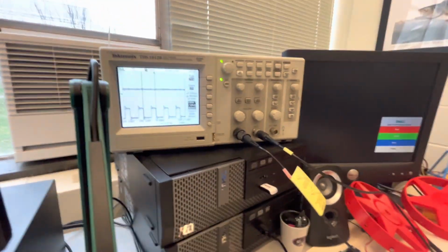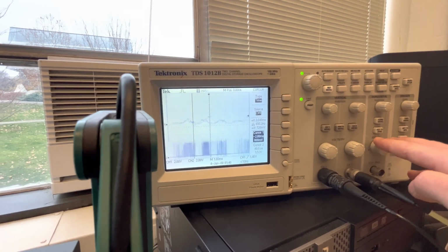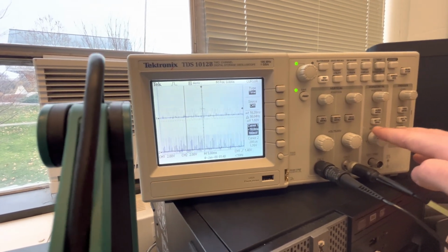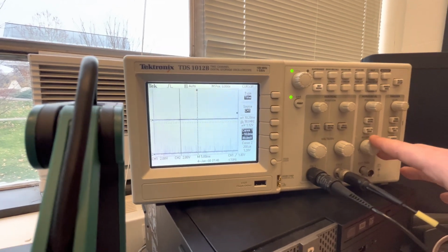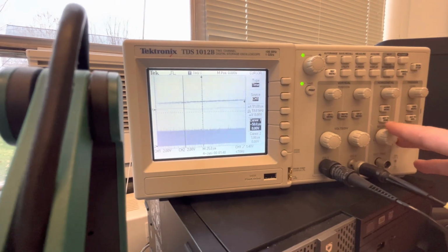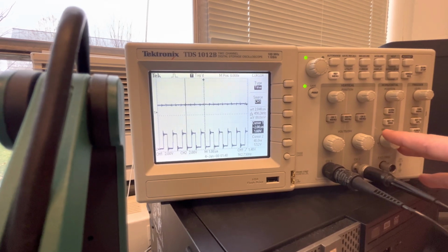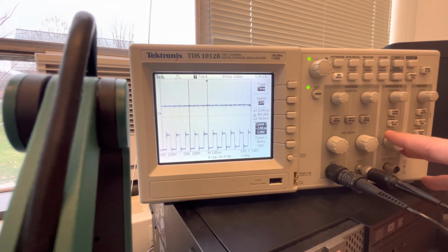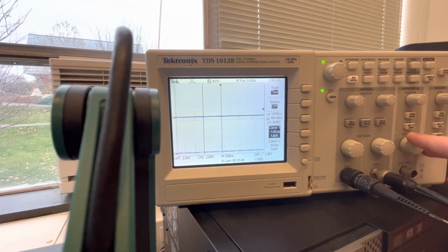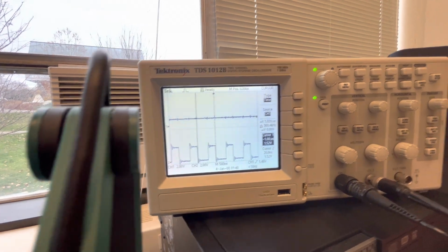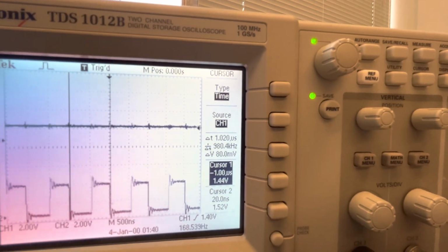And we can see this happening here in real time. So I'm going to zoom out, and as I speak, on the top trace there, you can see the voltages coming out of the microphone, and the bottom trace is showing the PWM approximation to that analog waveform at the top. And if I zoom in here, what we'll see is that as I'm speaking, the duty cycle of that PWM wave at the bottom is changing automatically, and the frequency of that PWM wave is just about 980 kilohertz.